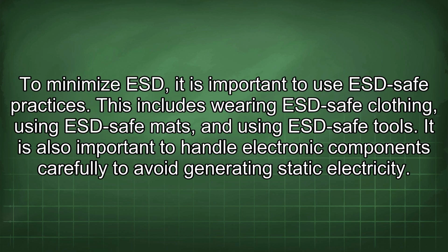To minimize ESD, it is important to use ESD-safe practices. This includes wearing ESD-safe clothing, using ESD-safe mats, and using ESD-safe tools. It is also important to handle electronic components carefully to avoid generating static electricity.